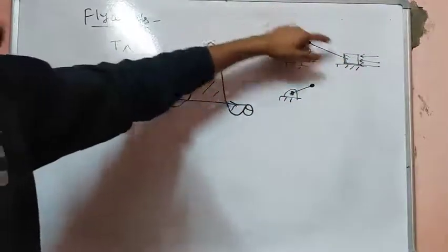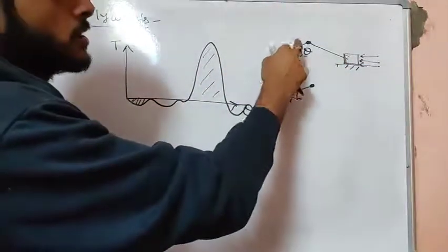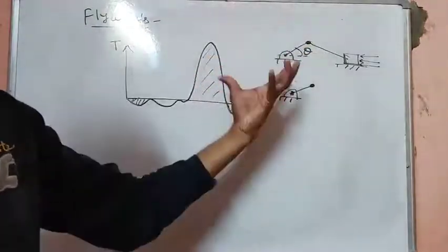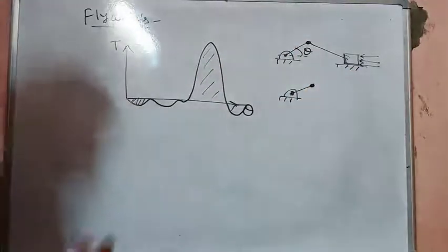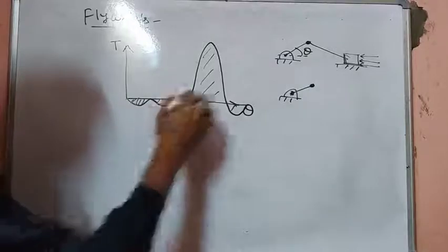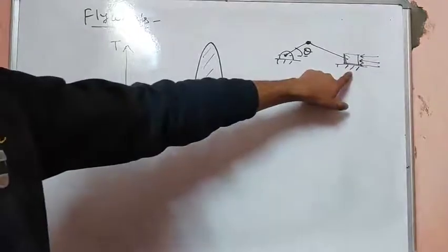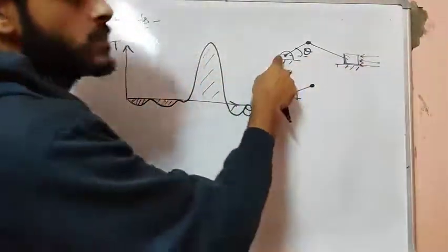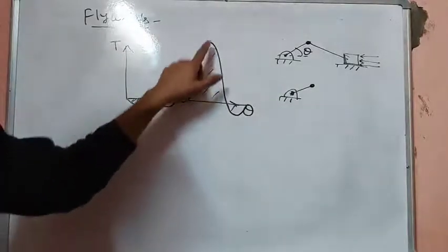When the crank is moving the piston, we have to externally apply some torque on this crank, so as to drive this piston. That externally applied torque has to come from somewhere. This is the required torque which has to be supplied to the system for the motion. During the power stroke only, when the gas pressure and combustion take place, the piston drives the crank, and the torque increases by a drastic amount.